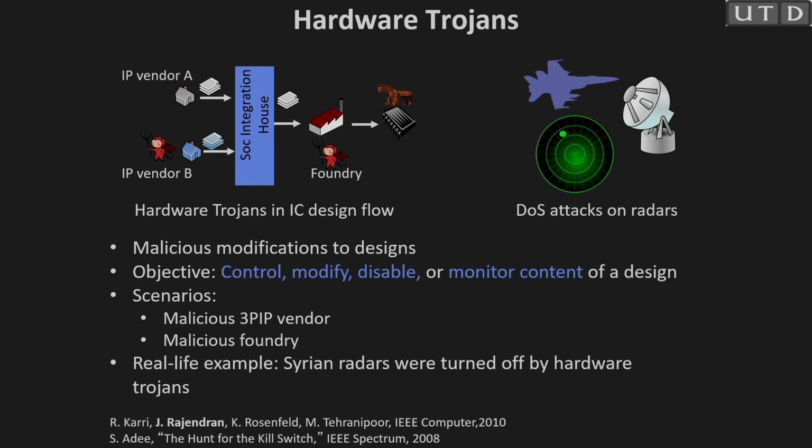As a result, even if this malicious modification happened, during testing or any other process it will be hard to detect those hardware Trojans, right. So, they will actually bypass the whole checking process, and then it will go to the customer side, and there they might do the damage. Okay. So, we already have many such incidents, and the interested reader can Google it, and they will get a lot of studies. So, since I am giving my layout to the foundry who will do the fabrication, they might insert a hardware Trojan in your system, right. So, this is one of the security risks.